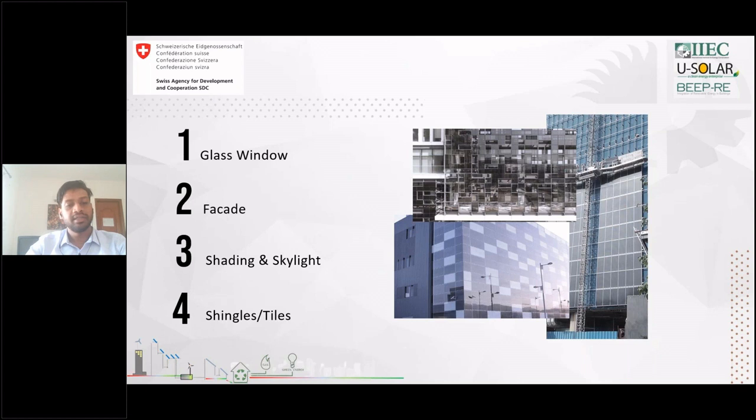One of the most widely used and scalable types of BIPV installation is the replacement of facade structures. Most high-rise buildings and greenfield projects make use of facade glass integrated into the building. Replacing these facade glasses with frameless solar modules will offset your initial upfront cost and have the added advantage of generating power for the same installation cost that would have been incurred for a facade installation.